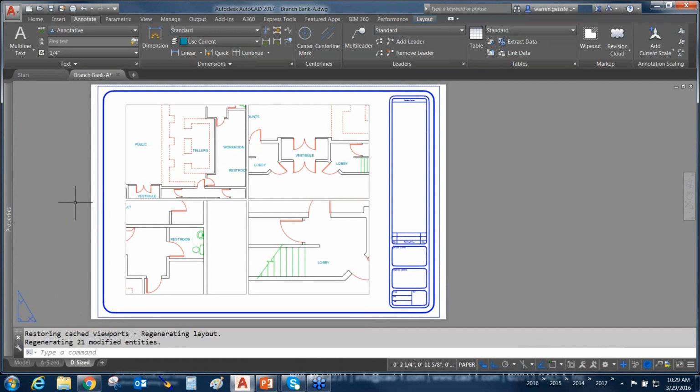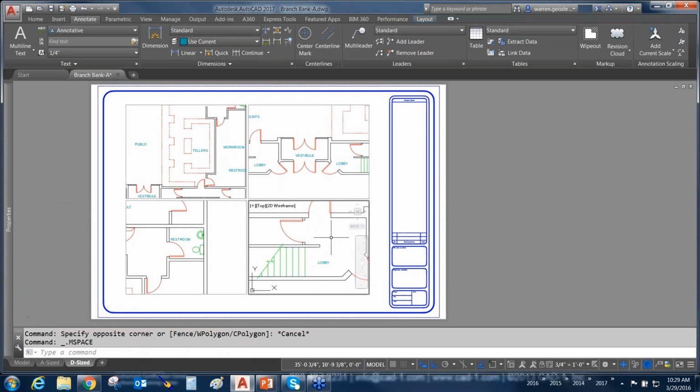And as I mentioned, when I get this set up, everything will be set up appropriately. Now, the last thing about annotative scaling that I do want to mention is, and you've got to be very careful with this, one of the reasons that the program will show you the ghosting, as I showed you a moment ago, that selection anno display, is because every one of your scale factors for each piece of annotation has its own grip.